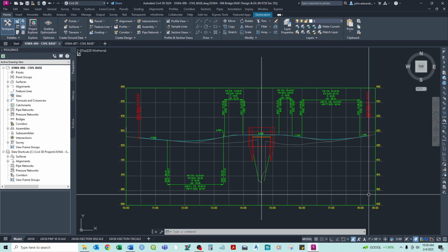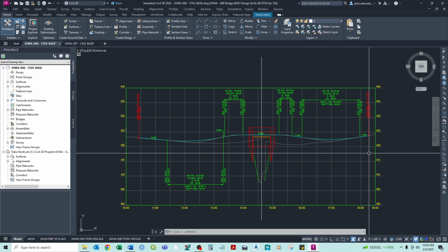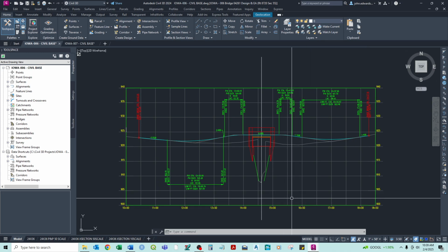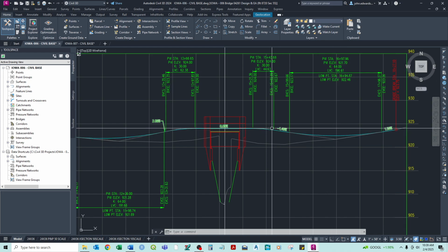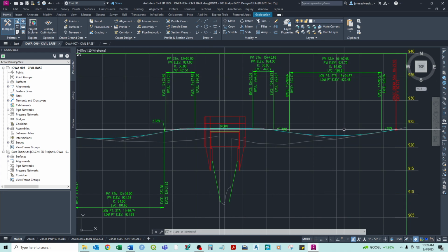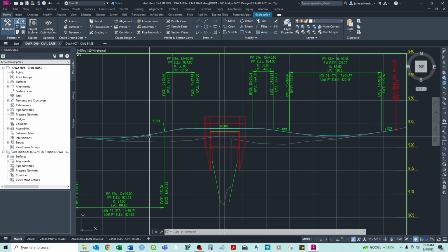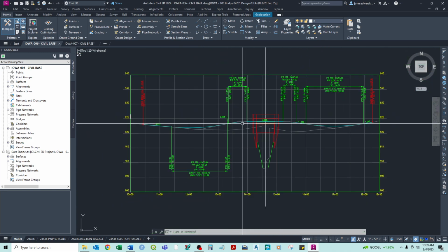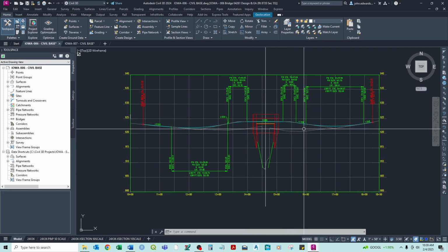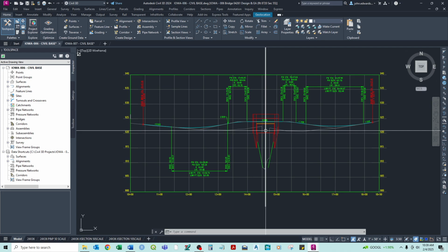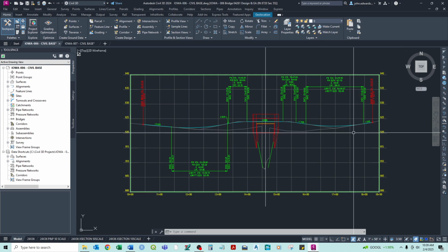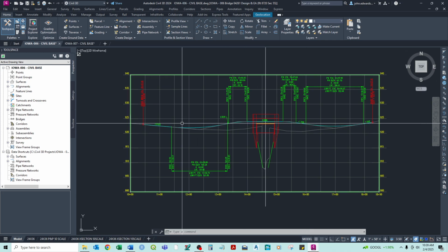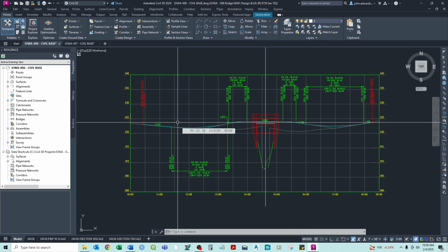Our Y direction is scaled up by a factor of 10 compared to the horizontal, so that's why that looks weird. But that helps us see our profile working a little bit better. We've gone in and since had to raise the road up to accommodate the bridge. It's got these very deep beams, and we finished the set profile. So from here now we're ready to move forward.